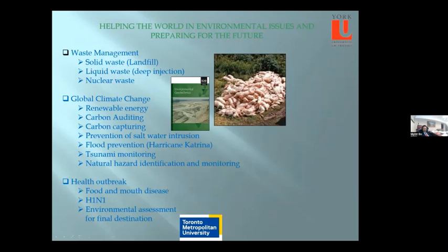The geotechnical engineer has to look for a suitable ground location to dispose of the dead animals and contain the contaminants and leachate. They also have to look for suitable cover material to minimize infiltration, and install many monitoring wells upstream and downstream to monitor the migration of pollutants and leachate, to prevent them from entering the aquifer which is used for drinking water.